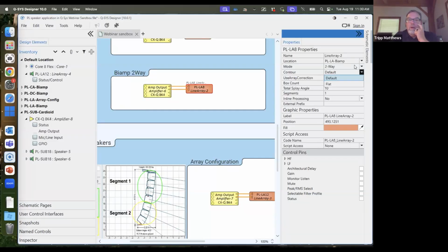They do come in as one speaker, so they'll come in as a CA, a DC and an LA, and you then tell it in its properties what horn patterns you're using in the EASE or EASE Focus, and then what model you're driving. They compiled them into one file for all the series, and you have a drop down under the filter section of EASE Focus to pick the horns that you're using for the DCs or the actual CA box from a drop down menu.